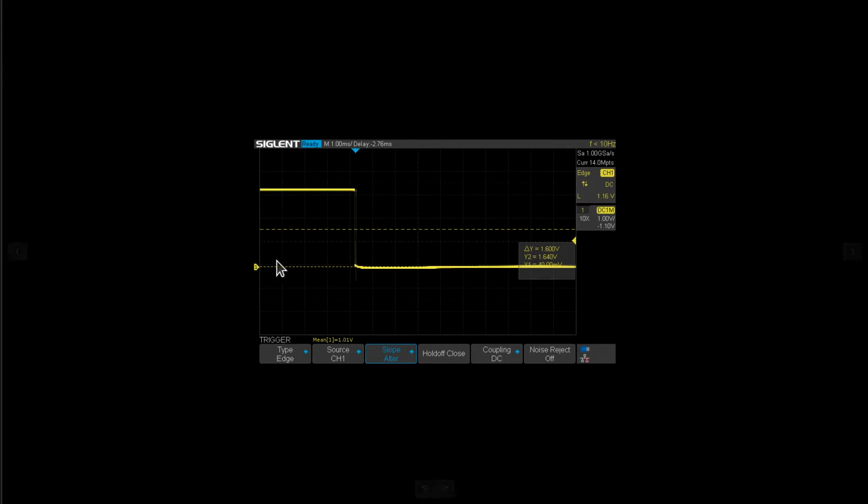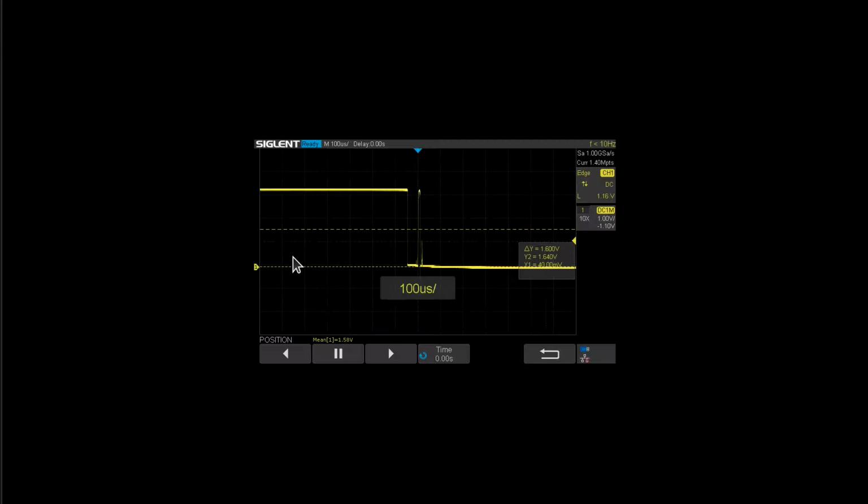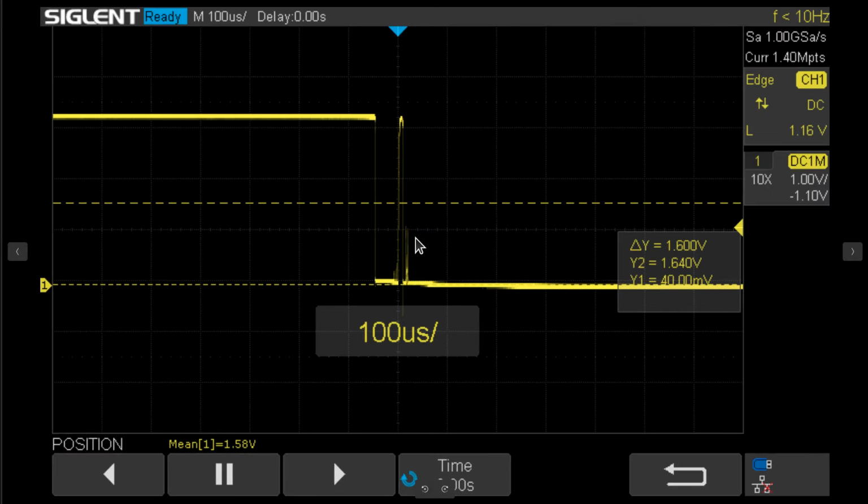And then you'd be fine. Here's another one that's looking like about 1 millisecond. What's this one? Here's one where we've got 100 micro. So yeah, that's probably me zooming in on the previous one by 10 to 1. This one is really nice because, again, if it's a human speed button press, all you need is 1 millisecond, which is almost the whole screen.